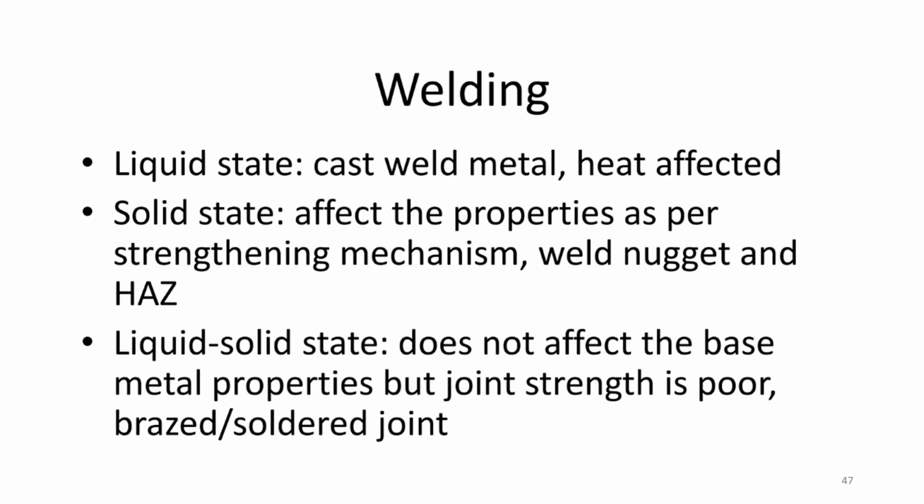In case of welding, you can have different types of welding, and based on that your properties will vary as well. In case of liquid state, solid state and liquid solid state, you will have different types of properties. In case of liquid solid state, it does not affect the base metal properties, but joint strength is poor. Brazed and soldered joints are poor and they break easily, so we won't be using these joints where you require better tensile strength.